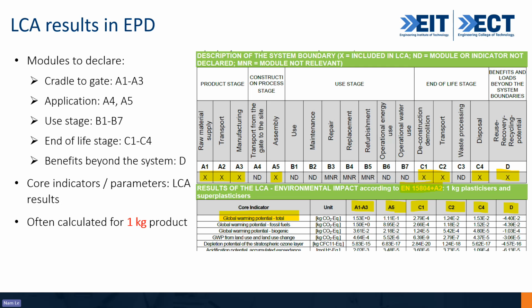Okay, and then the end of life stage is when the concrete, together with the admixtures inside, will be disposed of or sent to landfill, and then we also have all the processes like transport or treating the waste at disposal, right? And also there are some benefits beyond the system. Module D is when sometimes concrete is recycled back to make either aggregate or backfill somewhere, right?